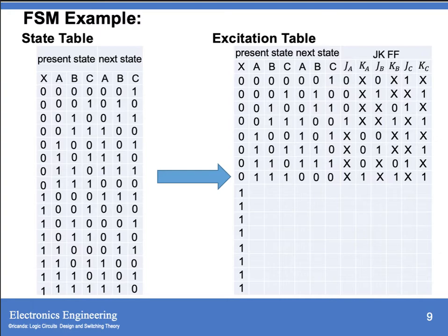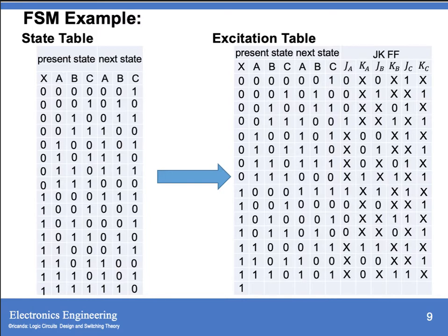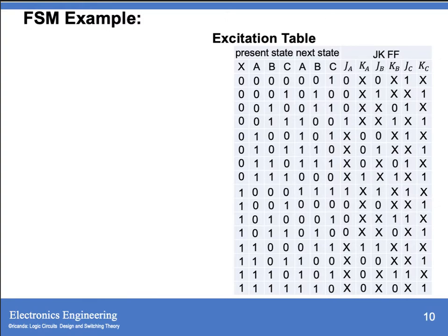so we have your first present state going to the next state, at your flip-flops A, B, and C, that is 0, 0, 0. So the next state is 1, 1, 1. So this is now the combination of your flip-flop JA, KA, JB, KB, JC, and KC. And from 2 to 1, from 3 to 2, from 4 to 3, then 5 to 4, then 6 to 5, then 7 to 6. After this, we are going to get the equation in each input of your flip-flop.